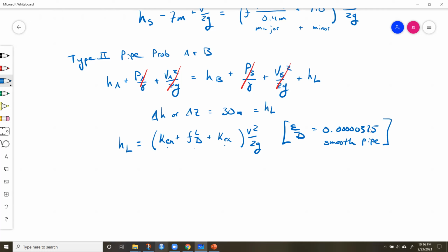It might be off the chart, in fact. So you go to the bottom of the Moody diagram, you get an f. If you go straight across, assuming fully turbulent, 0.015. That gives you a Reynolds number of 8.5 times 10 to the fifth.